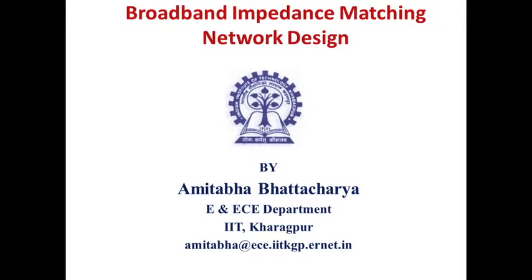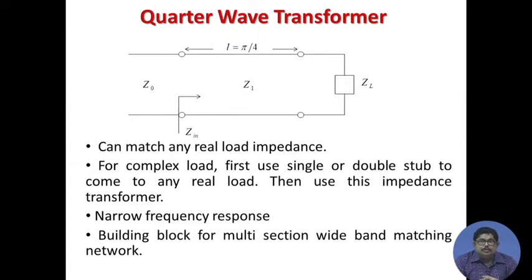So, wide bandwidth systems are necessary. So, impedance matching networks in microwave frequencies also need to increase their bandwidth. How to attempt that bandwidth, briefly we will touch upon in this lecture. The element by which that is done or can be done, one of the simple schemes, is called the quarter wave transformer. It is basically a section of a larger scheme.